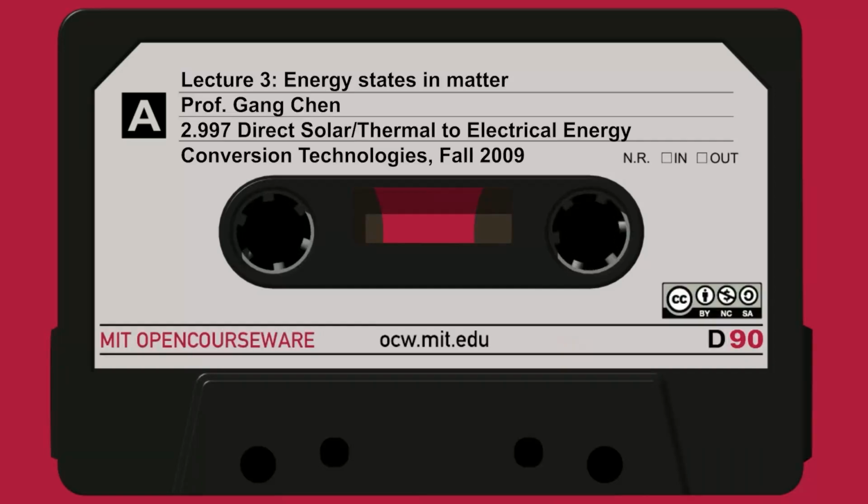And so if this gap is a few electron volts, much larger than kBT, there is very, very little chance the electron can come over here due to thermal energy. And it's an insulator. Glass, for example, is an insulator, and the gap is about 4 to 5 electron volts.